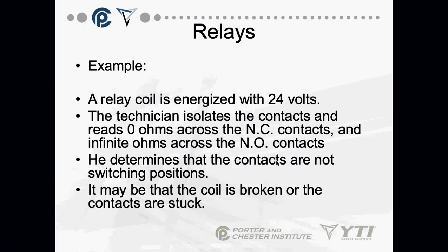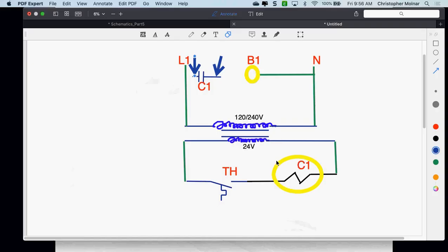Okay? I don't like playing around inside circuits, so I don't like using an ohm meter anywhere near a powered circuit. So another way to do this whole thing is to do it safely with your voltmeter. If I have my voltmeter here and here, and let's say this is 120 volts, not the 240. Okay, it's the 120 volts.